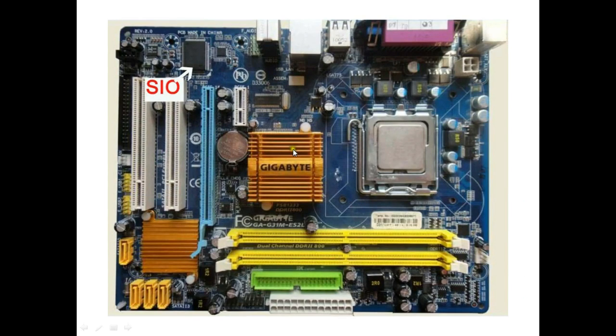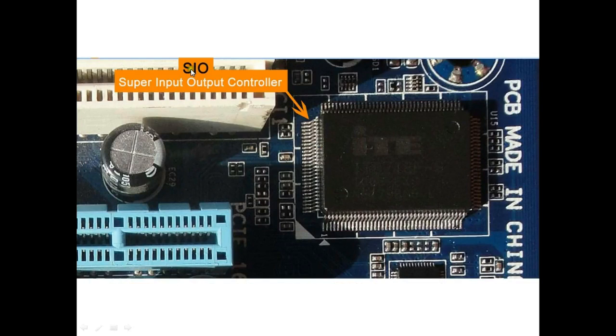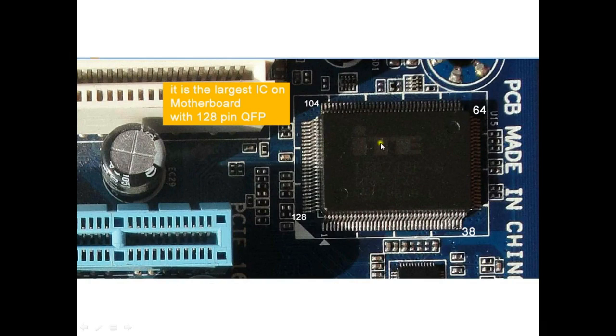So after the chipset, the largest IC present on the motherboard is the SIO chip. SIO stands for Super Input Output Controller. It comes in a package called QFP package, quad flat pack. You are able to see the pins here. In BGA type the pins are not visible to the outside, and the SIO chip in a desktop motherboard always comes in a QFP package with 128 pins. Total number of pins is always fixed at 128 pins.